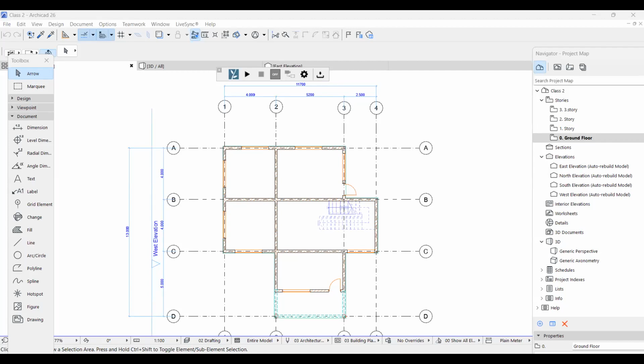This submenu here has a lot of wordings. But the last one asks, would you like to change the default settings? I think you can click here so that you can see which are the default settings. These are the loadings, the BS8110 settings. These are the load factors that you use.